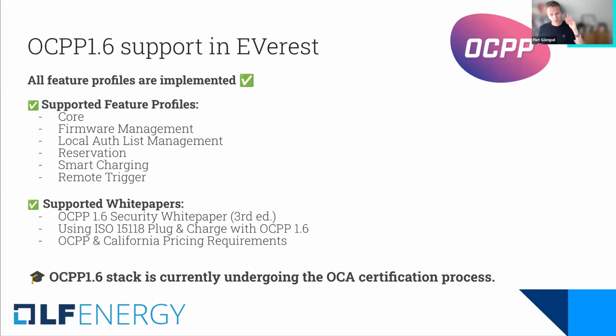So if you're using EVerest, you get full OCPP 1.6 support, including the feature profiles core, firmware management, local auth, list management, reservation, smart charging, and remote trigger. And there's also support for the OCA white papers for extended security features, ISO 15118 plug and charge, and also California pricing. And currently, the OCPP 1.6 stack is undergoing the OCA certification process.